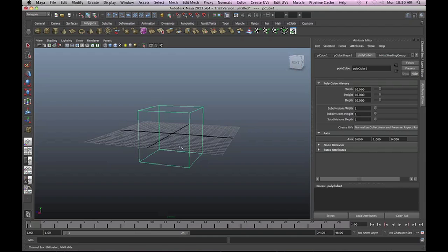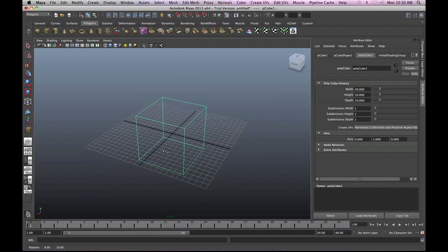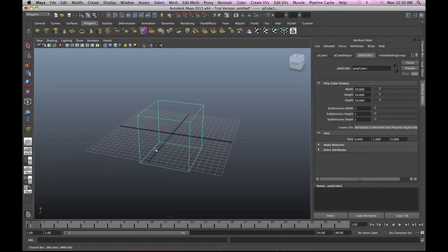We're having a little trouble seeing our cube here because it's just in wireframe mode right now. If you want to see the whole cube, press the number 5 on your keypad. That'll fill it in. You can switch back and forth between this and wireframe mode by using the keypad numbers 4 and 5. If you press 6, you'll be able to see the textures of your object. We don't have any textures yet, so it looks the same as it does in 5. We'll get more into that later. Go ahead and press 5 so that you're not in wireframe mode or in texture mode.